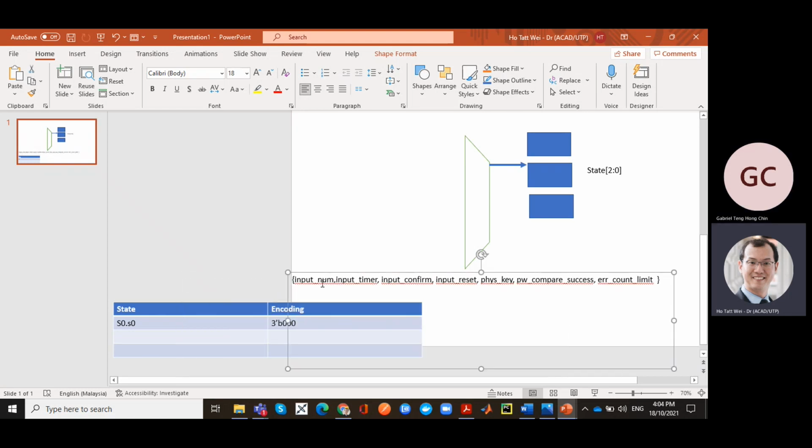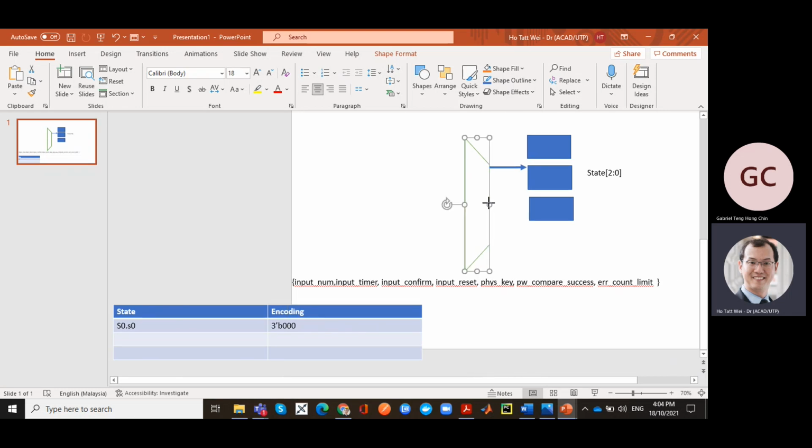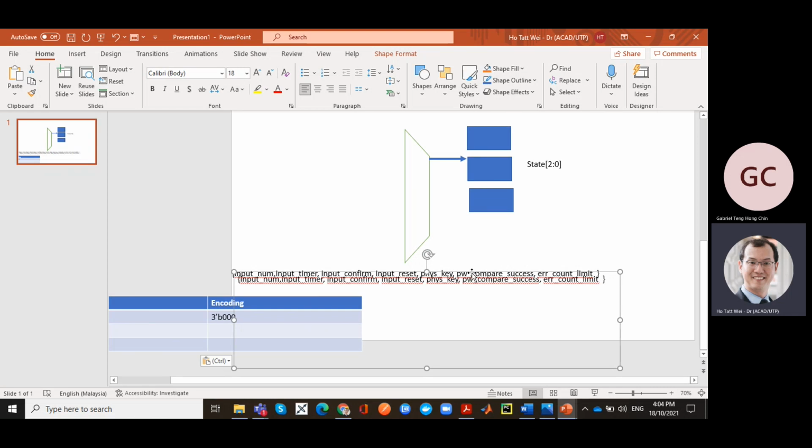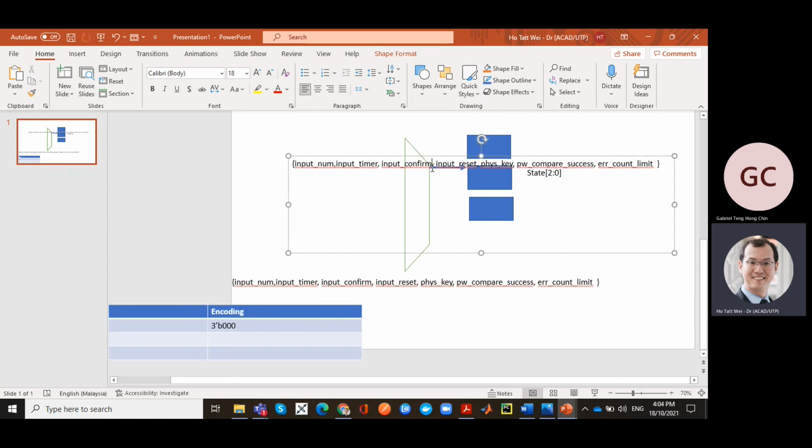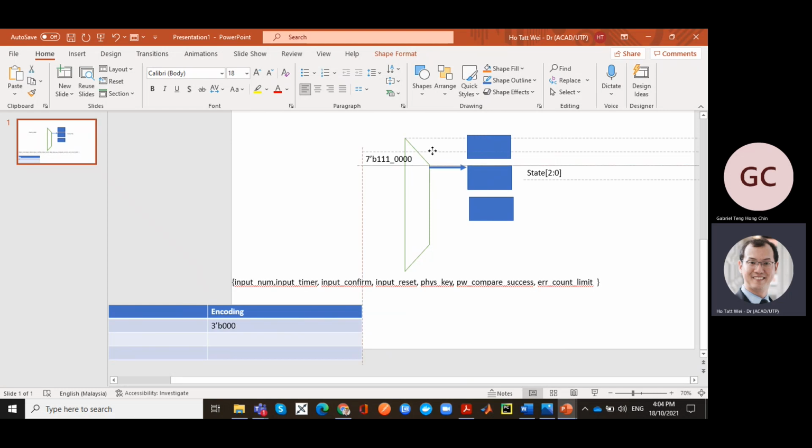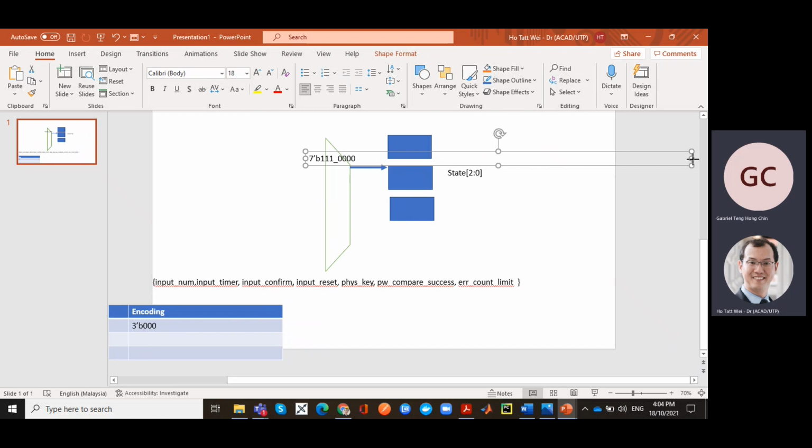This is a great example. So how many bits do we have here? 1, 2, 3, 4, 5, 6, 7 bits. So these options you have to list down as 7 bits. I would encourage you, because this is easy to see as bitwise, to list all your conditions out. You basically have to put 7 bits, 7'b1110000. So you will have 128 conditions here. You got that? Okay.